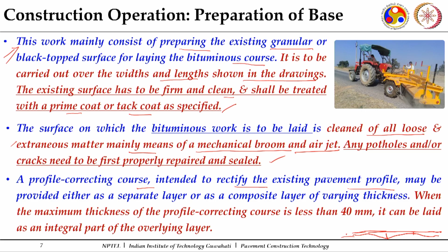So, in that case I will preferably go for a profile corrective course. Now, depending upon how much profile corrective course thickness is required, depending upon how much irregularities are there in the surface, we can use the same mix or we need to go for a different mix. Then it may be a binder course in that case, or a profile corrective course.